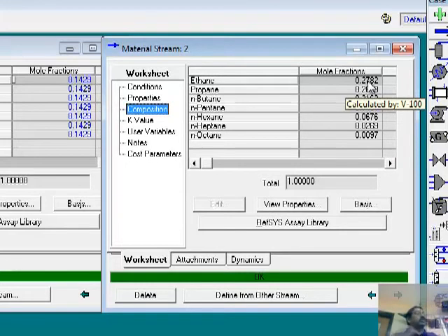Now you have a tool where you can change the temperature, change the pressure, change the vapor fraction, any of those 2 degrees of freedom, and look at what is the product that you are getting. Okay, this is what a typical process engineer would do most of the time. You'd be trying to optimize your performance by playing with the degrees of freedom that you have to meet a certain output target criterion that you have. Okay, any questions?